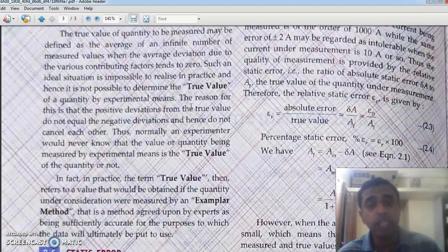So that is why we take so many trials, so that we can verify the set of readings. Suppose we take 7 readings, 5 readings may be consistent, and the remaining 2 may not be consistent. Those 2 readings we may discard. The 5 readings which are consistent, or which are coming as a group, we take, and we take the average. So the highly inconsistent readings we discard. That is another advantage of taking so many trials.